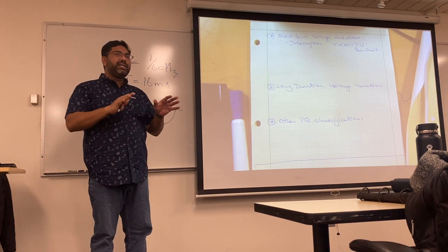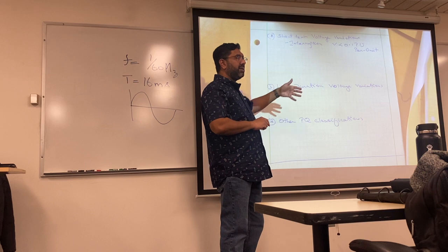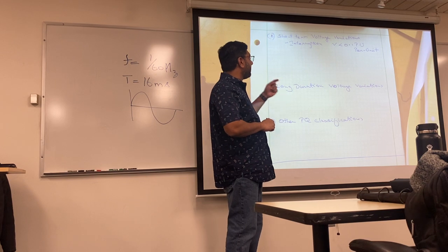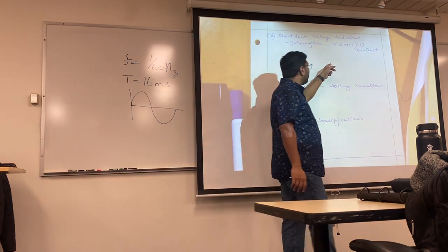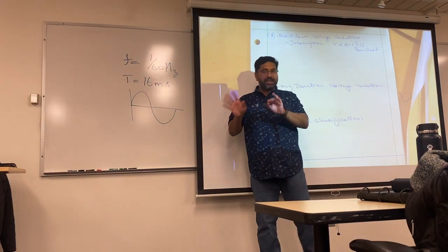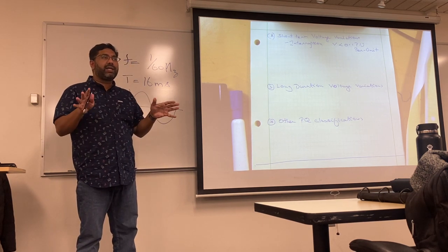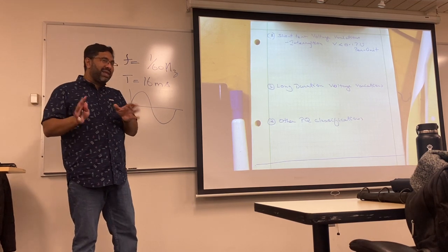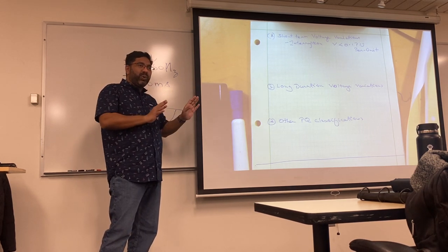Anyways, rather than dealing with all this jazz where I say that, hey, Pacifico operates their system at 13 kV, PG operates at 12.48 kV, what we have decided is we will come up with one unit or one voltage for the entire system, and we are going to define everything else based on that. So how you define your per unit is a lecture by itself, we'll come to that. And there are certain ways that we say that, if there are 18 students, I want to see 18 different per units, because that's your system. But at the end of the day, you will just give up and figure out, okay, there is just one better way of doing it, and you'll just go with that.